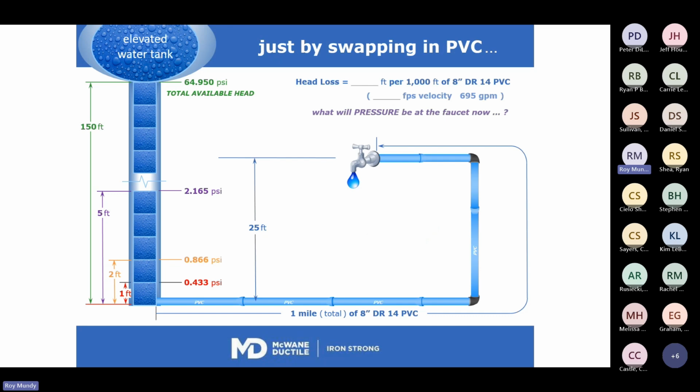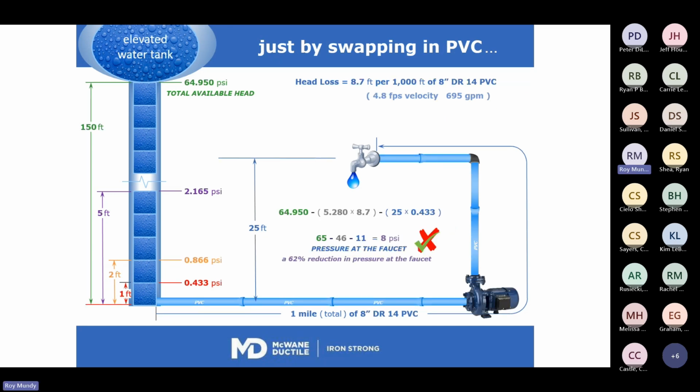On the other hand, if you look at PVC pipe, because of the head loss criteria, you're going to have only 8 PSI. That all is due to the fact that you have a lower inside area. What do you have to do to overcome that? If you have PVC, to get to the 21 or 22 PSI, you have to apply energy.